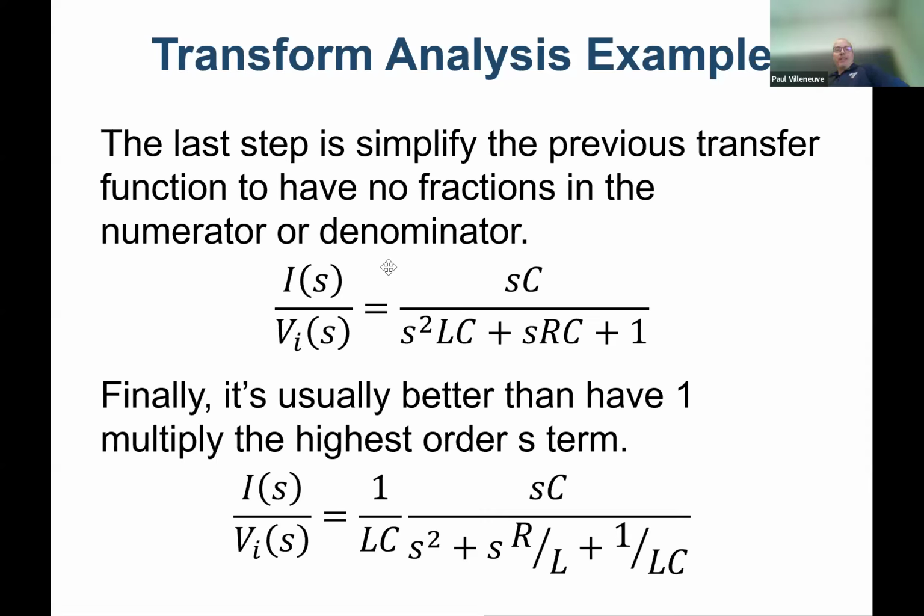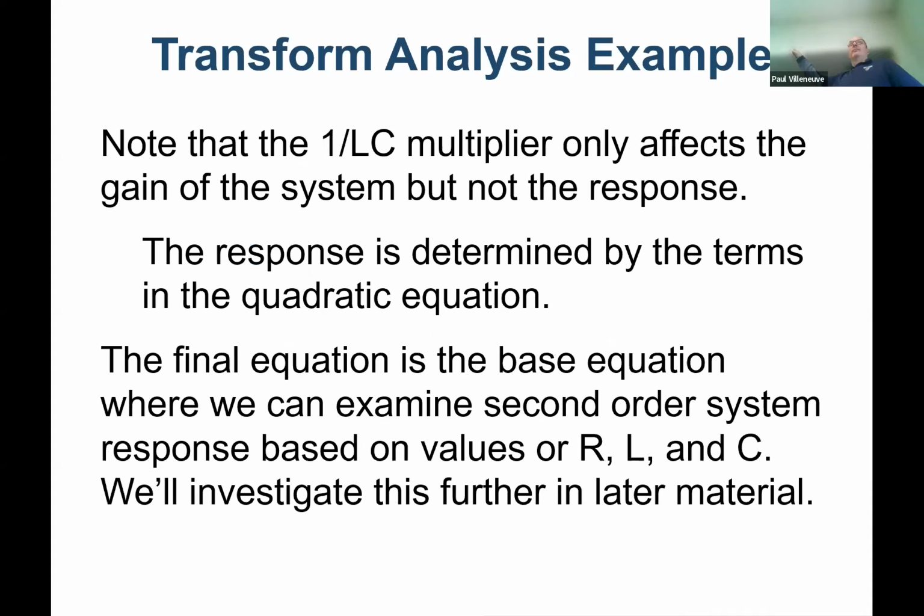That's no problem. So here is our circuit, and basically we have a second order circuit where we have to use the quadratic equation and do all that stuff. It's going to be either two decaying exponentials, or one decaying exponential with potentially a ramp if you have repeating roots, or you're going to end up with a complex sinusoidal waveform output. That's how you can get an oscillatory response in an RLC circuit. You can energize an RLC circuit with a DC source, and if you monitor the current, you can get some oscillation. We'll talk about that more in detail next semester.